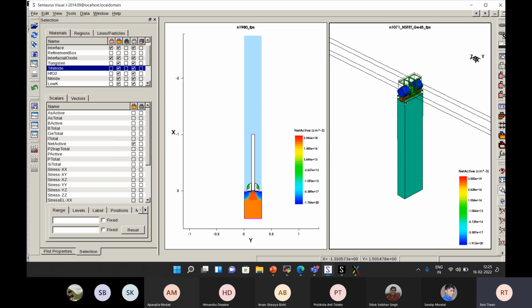In this simulation, you see the blue things. Can you see these blue things? Yes, sir. These blue things are the source and drain, and they have germanium content, basically silicon germanium, and this gives some strain in the channel so that the mobility of the PMOS transistors, or P-substrate transistors, goes very high. In that scenario, you need to consider this because it is not symmetrical in this direction. You get some strain out of the 3D geometry, and geometry plays a role in the amount of stress or strain in the channel.